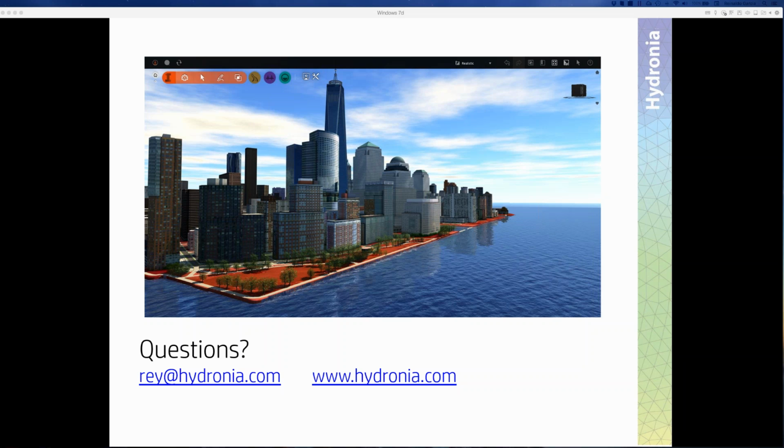A question: can we edit the flexible mesh in InfraWorks? Well, presently the existing version that is in beta now uses more or less uniform size triangles. As you saw in SMS, you can have quite a lot of detail and refinement. But in InfraWorks, the present version is only available in that way.